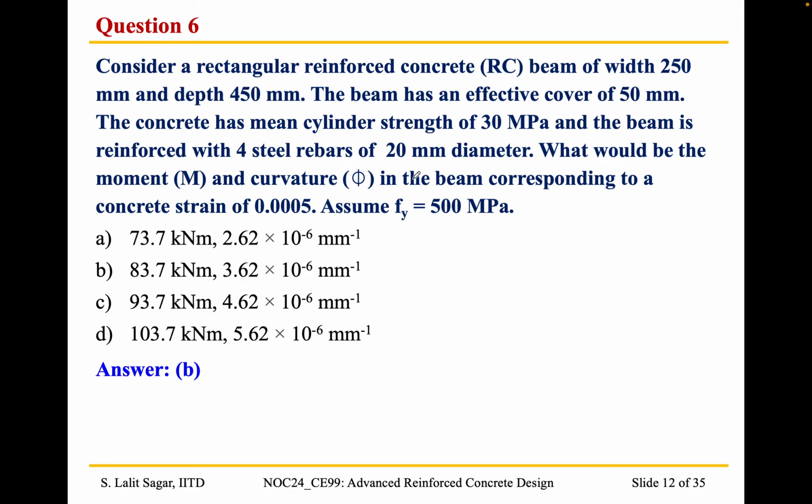What we can do is, if we consider a simply supported beam, again for convenience in the calculations, let's say that it is being loaded by any given load P. Since it's a statically determinate structure, we can find out the maximum bending moment at this point, so we have the value of m.